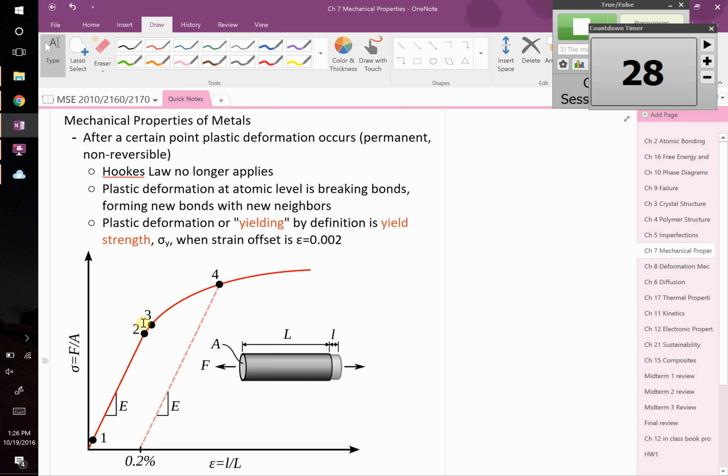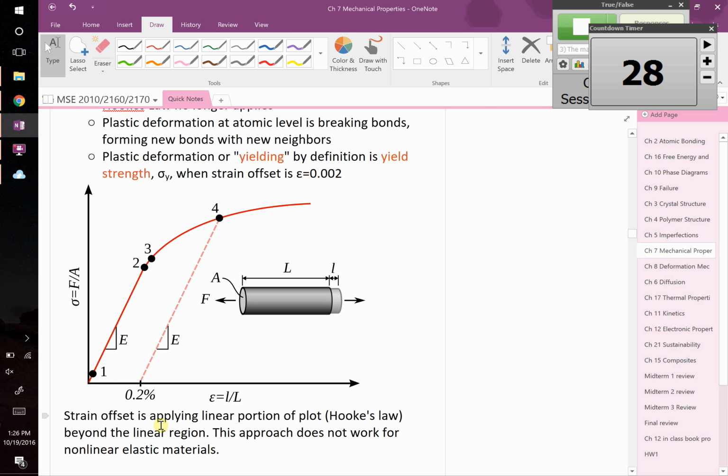Yeah, it's when plastic deformation begins. And that's a super hard thing to do because if you look at this plot, that's about at 0.3, right? Here's our Young's modulus, meaning you apply a load and you get some sort of strain. And technically, the very instant when it starts to have permanent deformation, that's when you have yield, the onset of yield. In reality, that's super hard to measure because it's going to be really, really small. So you'd have to have really, really sensitive equipment on there, right?